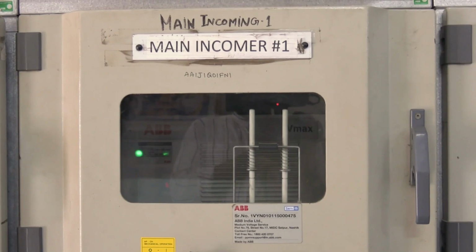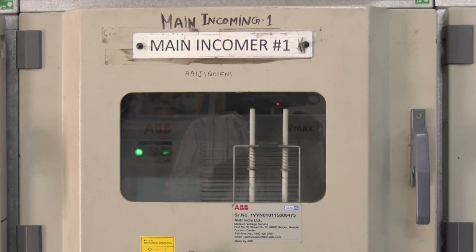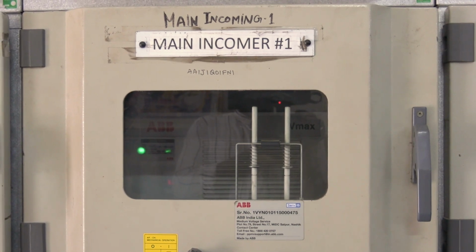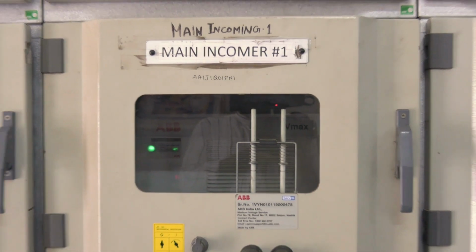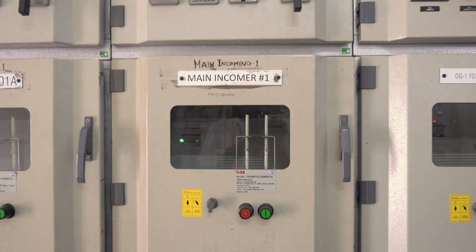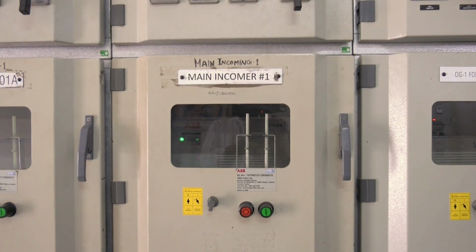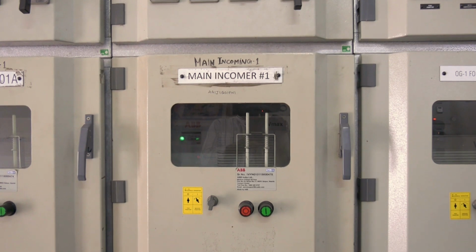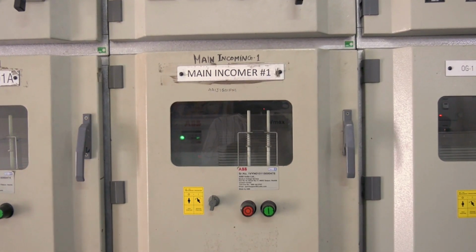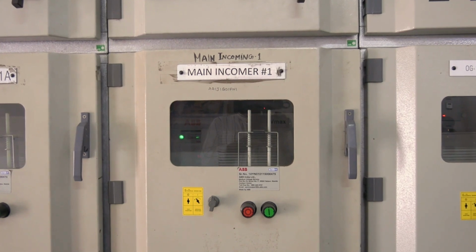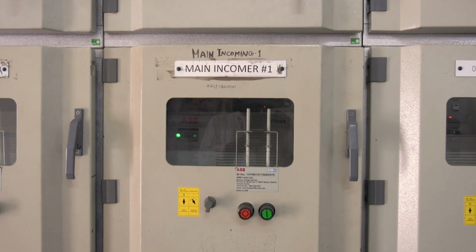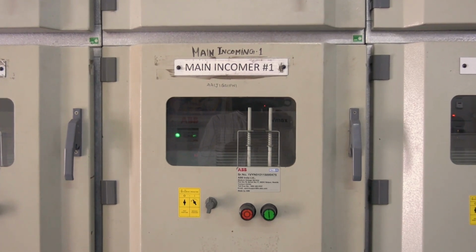This is the main incomer 1, which indicates that the power signal for the first transformer is routed to this panel. The mechanical operation switch here allows for manual switching between the test and service positions for the circuit breaker, ensuring safe testing and operational engagements. The label clearly indicates the position and directions for operations. Additionally, an emergency button is present for immediate action during any emergency situation.